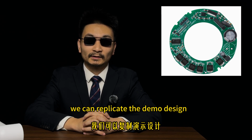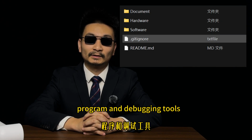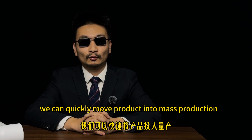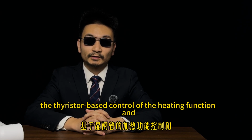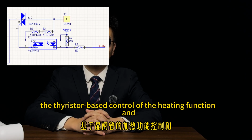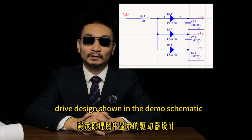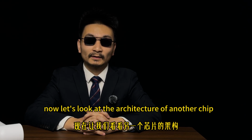We can replicate the demo design, and by using the reference program and the debugging tools provided by the chip manufacturer, we can quickly move the product into mass production. The thyristor-based control of the heating function and the half-bridge MOSFET drive design shown in the demo schematic are well worth studying. Now let's look at the architecture of another chip.